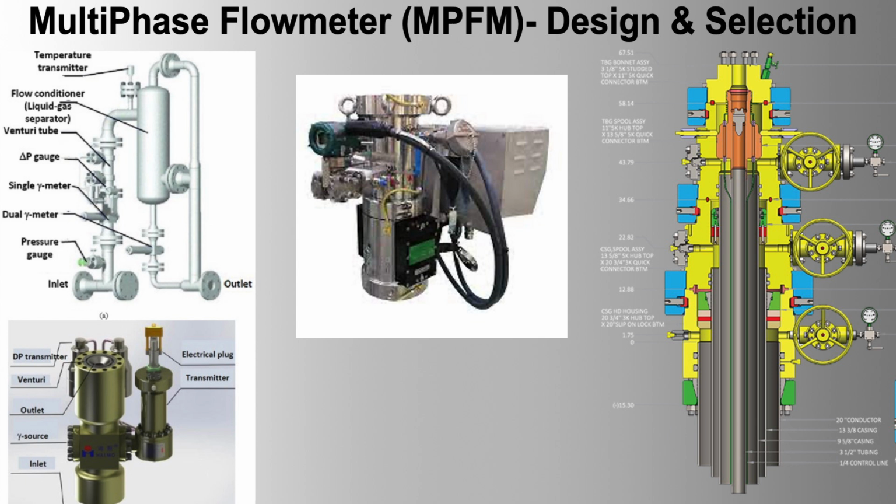3. Accurate allocation. Scenario: production data from several well clusters need to be accurately allocated for revenue distribution and regulatory reporting. Benefit: MPFMs provide precise measurements of each phase from every cluster, ensuring accurate allocation and compliance with regulatory requirements.